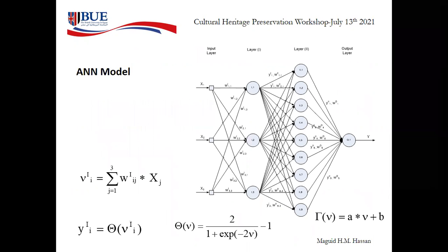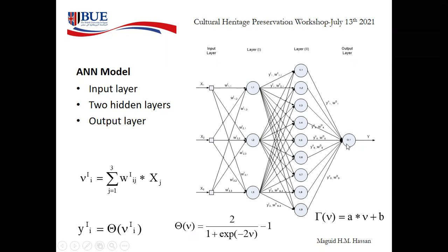We actually used two smart technologies to develop these pattern identifiers: artificial neural networks and fuzzy inference systems. So this is the first model, which is the artificial neural network model. It has an input layer, and the input layer is basically the inputs coming from the 3 degrees, which is the displacement of each level. And then 2 hidden layers. One has 3 neurons and the other one has 9 neurons. And then there's an output layer, which has a single neuron, which conducts a linear combination of all neurons of the previous layer.